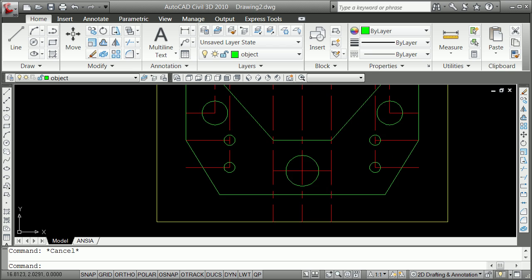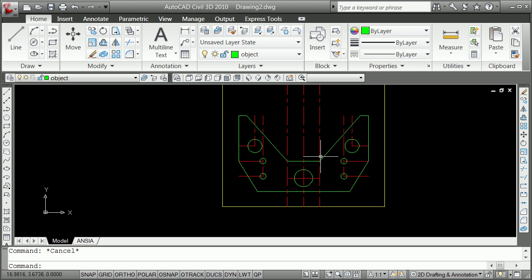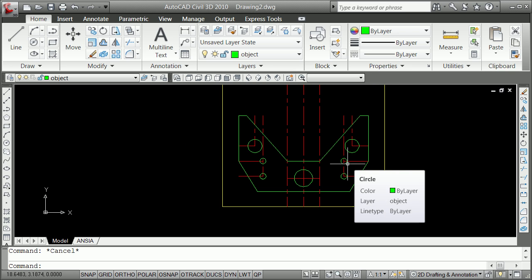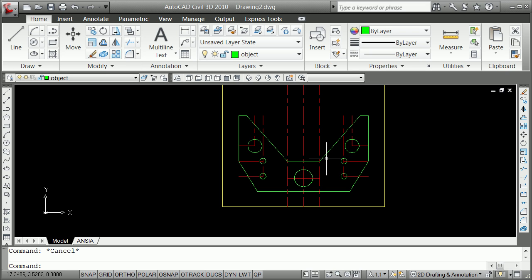Finally, the last step to this is going to introduce some small, tiny thing. And that is that it really doesn't make a lot of sense to have two short little lines here when they're in fact one line. So it's not a bad idea here to erase one of these and erase one of these, and then do fillet radius 0, grab here and here, space bar, grab here and here. Now we have this all as one piece.